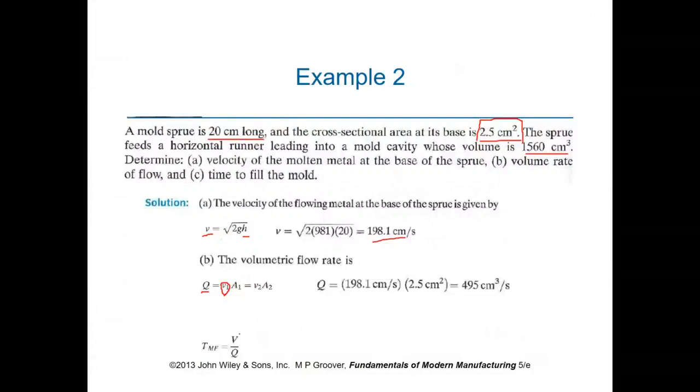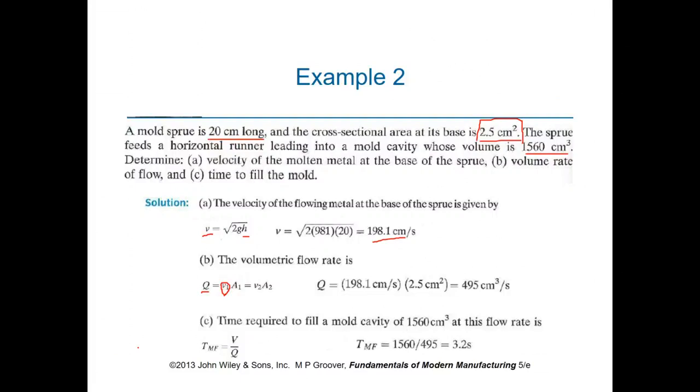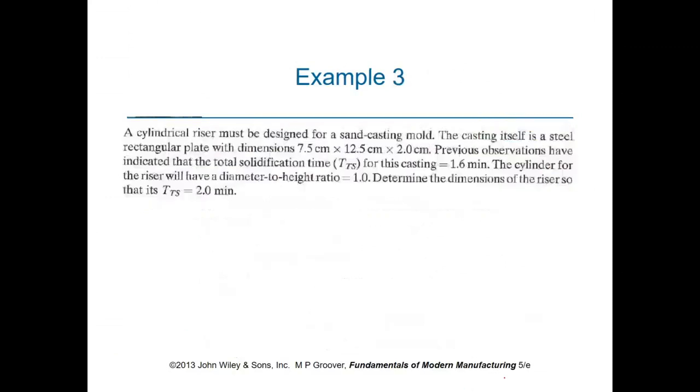Take the equation, the volume of the material to be melted, and also Q. Q was just computed, and the volume of the material is also given up here. So we substitute this value and also the Q that was computed, and then it makes it possible for us to compute the time that is needed in order to fill the mold. So we are done. Next problem, problem 3.